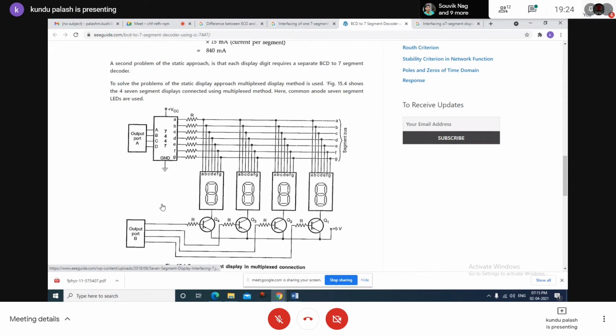In 8255, each port has 8 lines. So in effect, we can interface 8 seven-segment digits by this technique. Here the data line is only 4 because we are using the display decoder. Otherwise, it would be 8. If we omit the decoder, the 8 lines would be connected to port A, and port A has a maximum of only 8 lines.